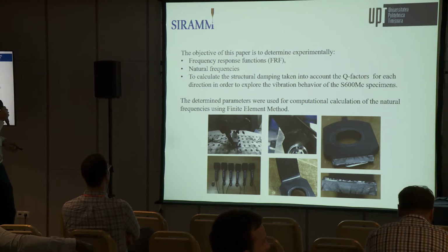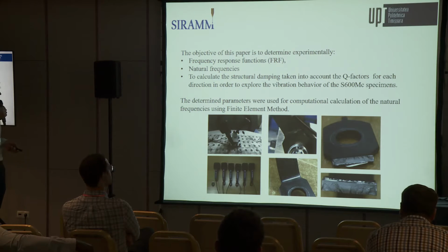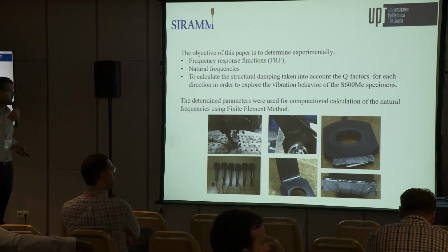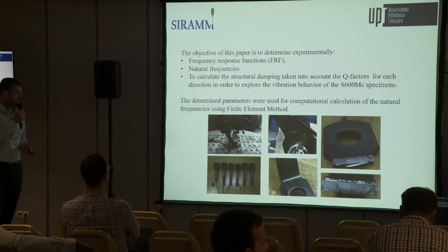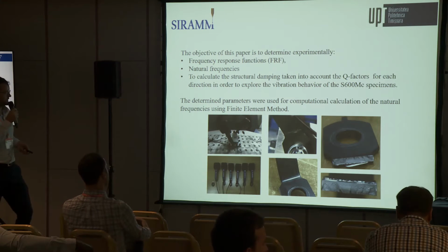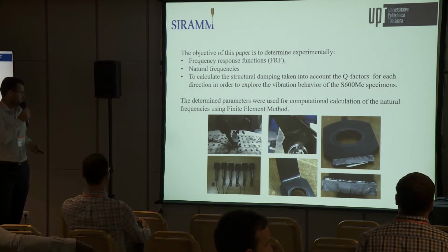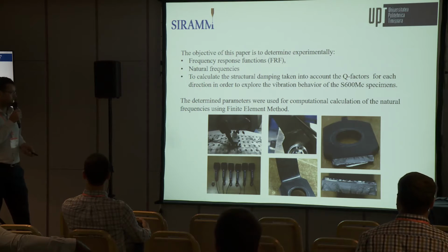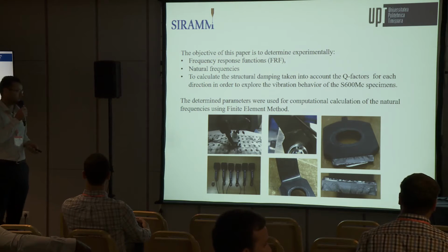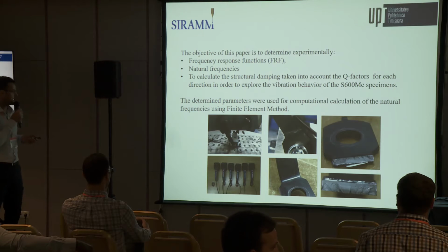The objective of the paper is to determine experimentally the frequency response function and natural frequencies, and to calculate the structural damping, taking into account Q factors for each direction, in order to explore the vibration behavior of the S600Mc specimen. In the end, the determined parameters were used for computational calculation of the natural frequency using finite element analysis.